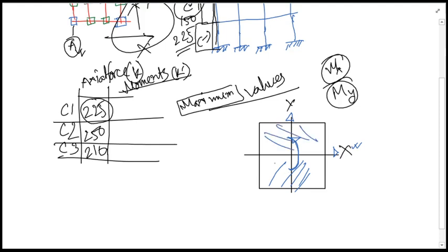So it tries to bend this surface with respect to x on that surface, and that moment that we are denoting as Mx. We say this one is Mx, and for our convenience, for the method we'll be using, we can say this is M1x. Okay, and the moment which is trying to bend this particular surface over this one, or vice versa, whatever it is, the moment which is acting with respect to this y-axis, say for example this is working in this direction, and that we will be denoting as M2y.